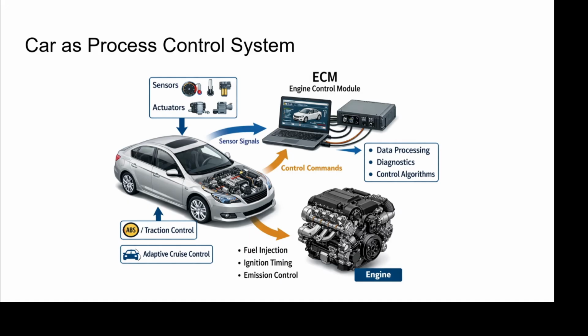And then we also have, in the factory or manufacturing world, the idea of automated control. So let's say the operator wants to set a set point of 12 gallons per minute, and the PLC manages all of the process variables to control the speed of pumps. That would be very similar to cruise control. So in a car, we're setting, say, I want to go 70 miles an hour as my set point. The engine control module will tell the engine and the various sensors and actuators what they need to do to maintain that. Then if we start going up a hill, the engine control module is going to tell the engine to speed up to maintain that speed.